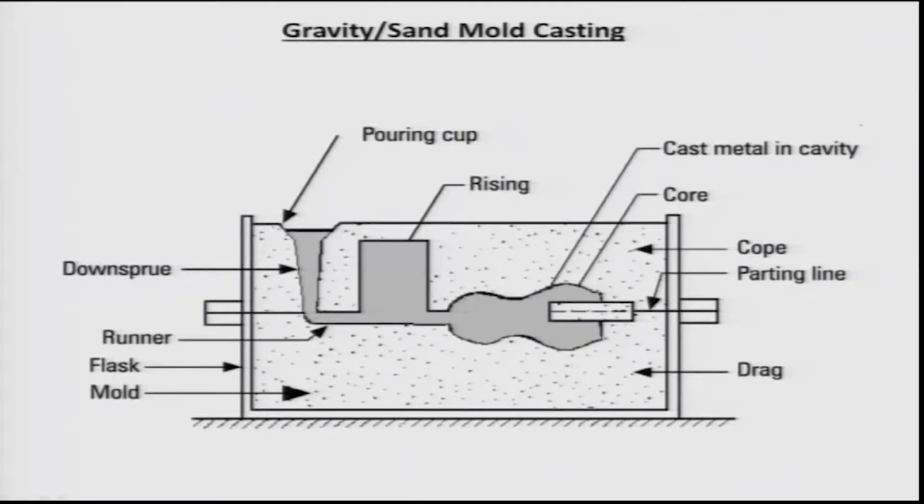Well, I do not want to give a complete lecture on how castings are made, that is a different course altogether. But let me tell you the basic important aspects. The liquid which is poured in the pouring cup travels to the cavity and then starts solidifying. And because of the sand mold, the walls of sand act as heterogeneous nucleation sites. And once the nucleation happens on the surface or the walls of the mold in which sands are present, the solid grows into the liquid.